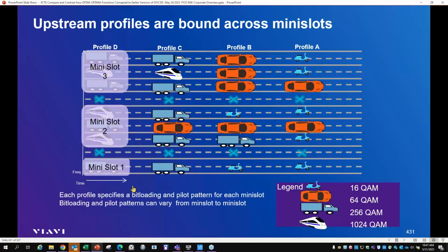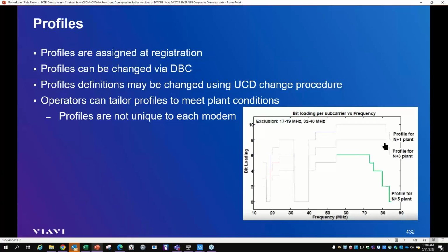well, that mini slot is an example, right? So therefore, in conjunction with the pilot carriers and certain patterns and how they're broken down into smaller groups. Remember, when the OFDM carrier transmits, it is still considered one symbol, then the next symbol itself. But those groups of symbols in combination with pilots are creating our mini slots and profiles as well, right? So it's similar to the OFDM carrier, but it's much more broken down, and we'll see how that looks when we look at it.